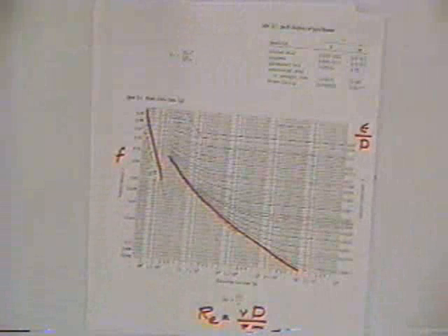And so, by definition, a smooth pipe is a pipe where, if you look at the roughness, this epsilon, the little height of the roughnesses inside the pipe, those roughnesses are small enough so that the laminar boundary layer, even if you have turbulent flow in the pressure conduit, at the contact between the liquid and the boundary, there will be a laminar boundary layer. Now that laminar boundary layer completely covers up the roughnesses. Then the flow turbulence never sees those roughnesses. And we call that smooth pipe.